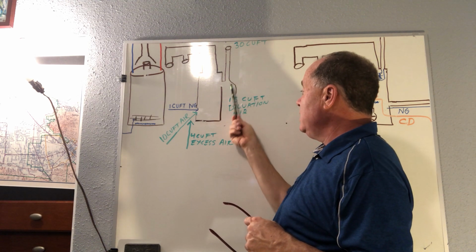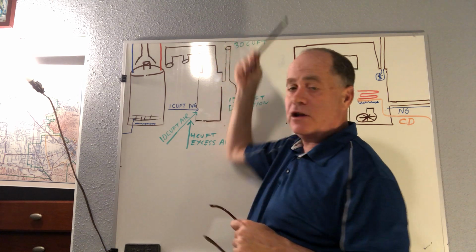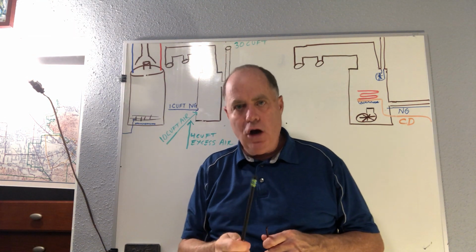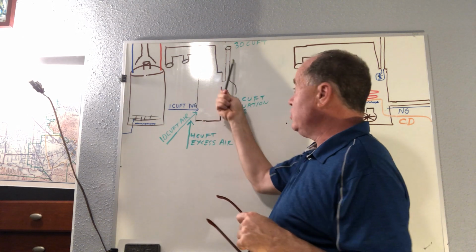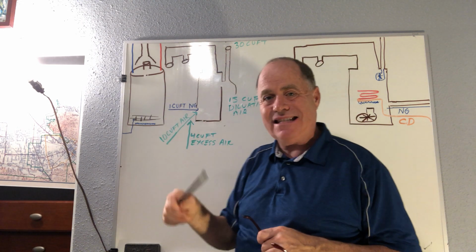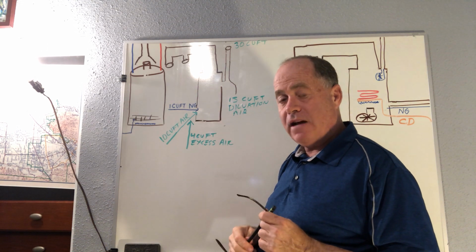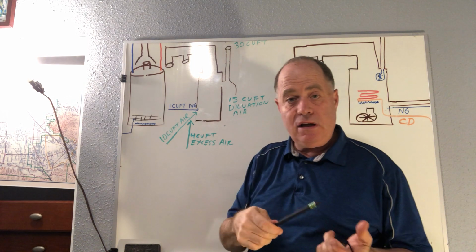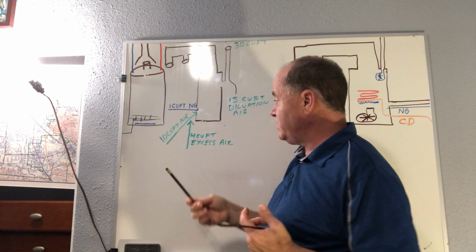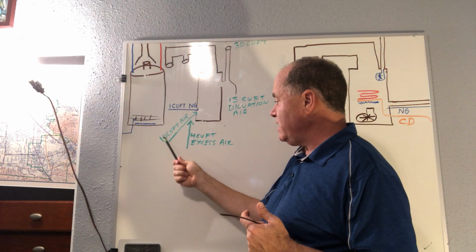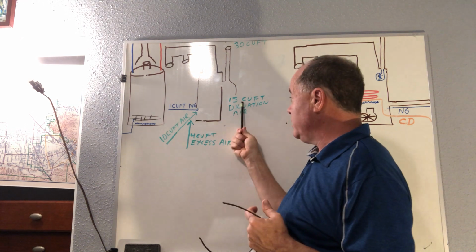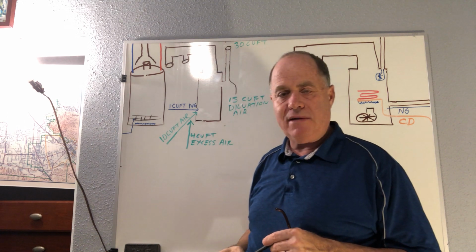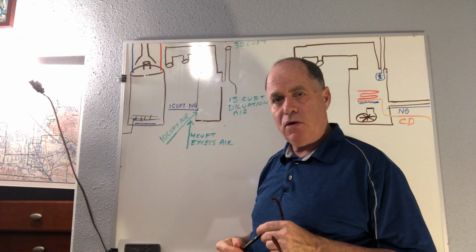Also, that helps move along the products of combustion. It causes the relative humidity to be lower here, so that you're not as likely to have water condensing onto your vent pipe or down below, and then it goes out. Whatever you put in, you get out. So here you've got 1 plus 10 is 11, plus 4 is 15, plus 15 gives you 30 cubic feet of products of combustion coming out the chimney pipe, okay?